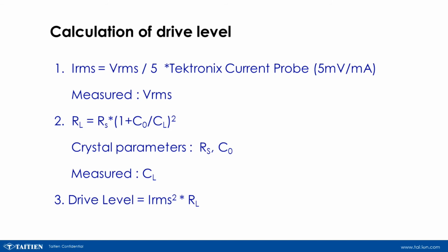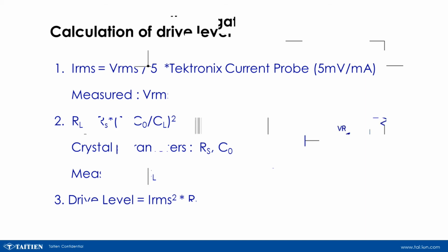The parameters measured above are the drive current, the crystal's parameters, and the load capacitance. Calculate these parameters for drive level. After obtaining these drive level parameters, we can understand whether the drive level of the crystal in the oscillation circuit is appropriate or not.